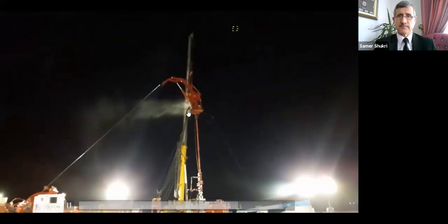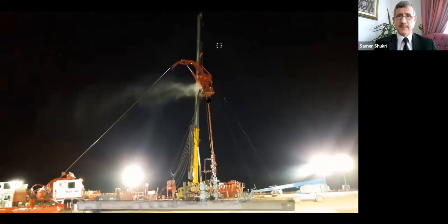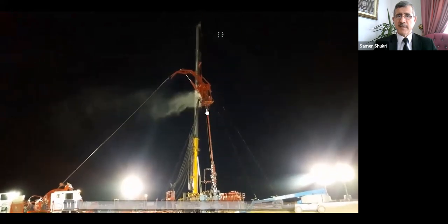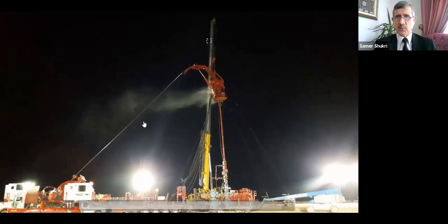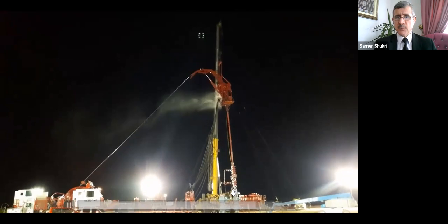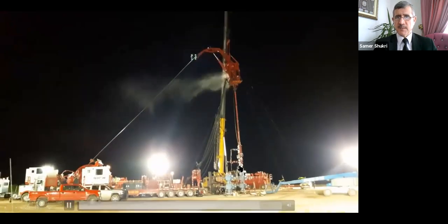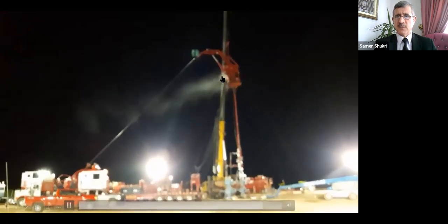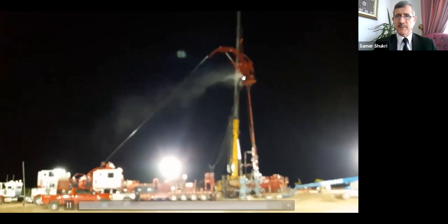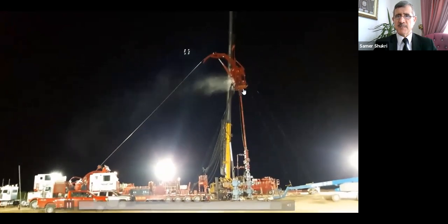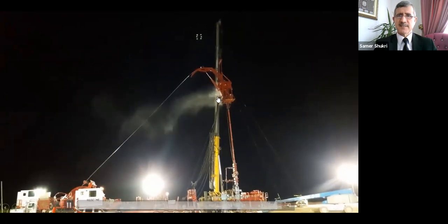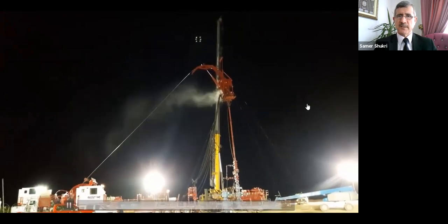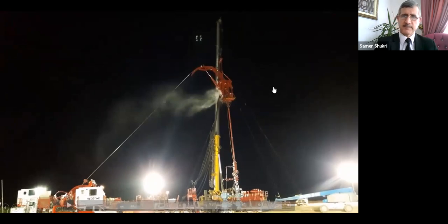You see, it is clear here. There is a stripper here below the injector head, and it is leaking. So we have to stop coiled tubing, close this BOP, the pipe and strip rams here in this area, and secure the well. Bleed off the pressure above it and replace the stripper above here. So it is not safe to continue like this. Quick action should be taken.